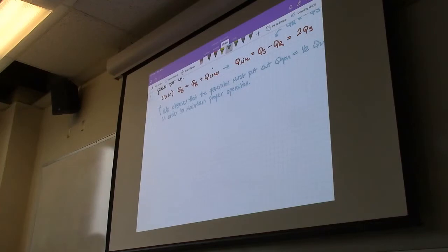Okay, so now section 4.6, we're slowly getting to the payoff, which is how we're going to apply this to looking at stability. I replaced the word stability with proper operation right here because when the generator goes from supplying 0.5 and drops to 0.49, that's not when stability is lost. As you move further and further away from that value, that's when you get closer and closer to losing stability. So proper operation is supplying half of that value, and once we get below that, we start getting into the danger zone for losing stability.